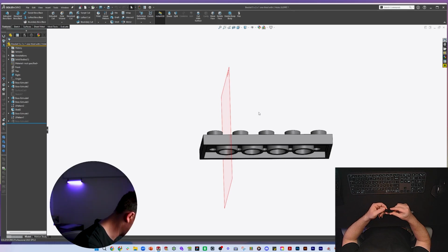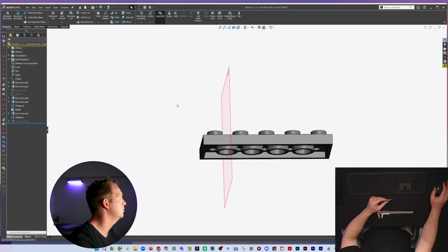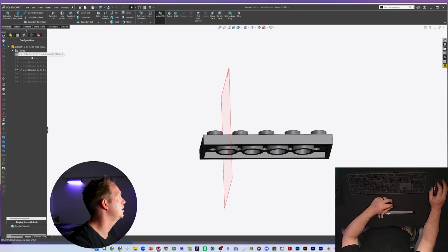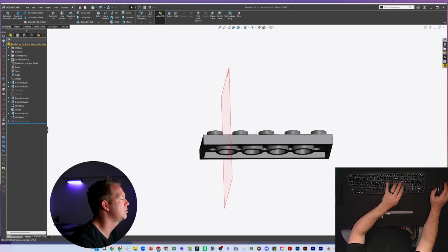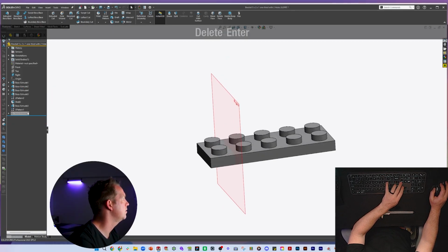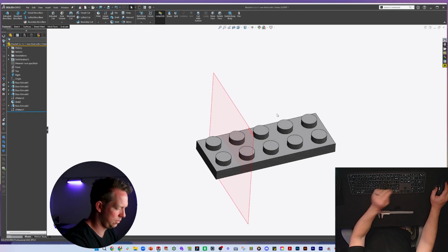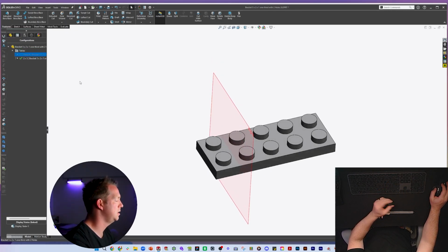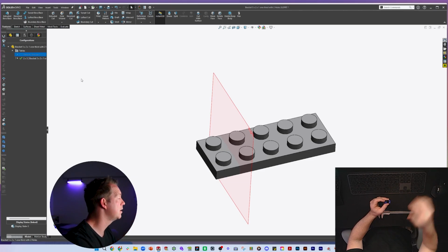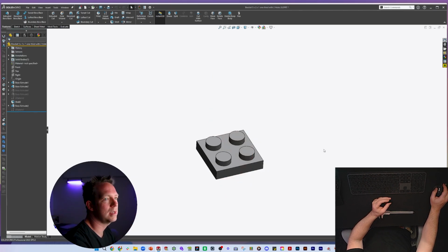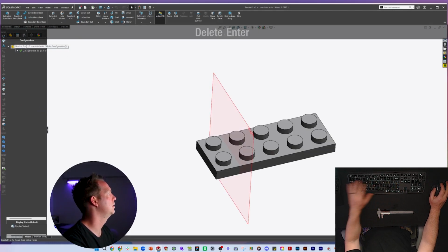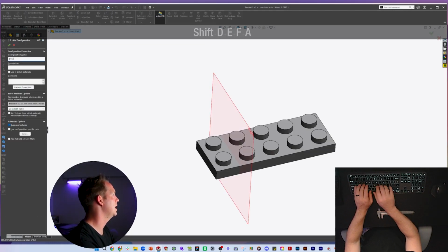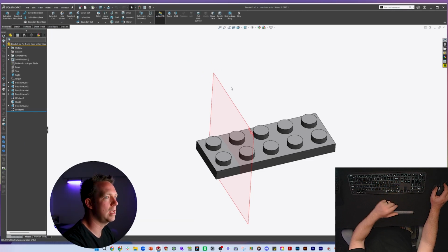Now the shell for this will be interesting, or the process of getting to where we need. In this example, I am going to delete the 2x1 configuration, and I'm going to delete most of the other configurations as well. And here's a trick: if you want your current version to become the default configuration, you can actually just delete default and rename it. Like if I go to default here, you can see half the stuff is turned off. But if I go to 2x5 and then I delete default and add a new configuration and name it default, then this is now my new default.